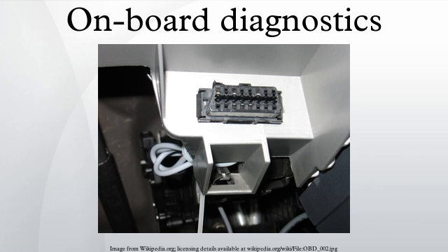OBDII diagnostic connector. The OBDII specification provides for a standardized hardware interface, the female 16-pin J1962 connector. Unlike the OBDI connector, which was sometimes found under the hood of the vehicle, the OBDII connector is required to be within 2 feet of the steering wheel. SAE J1962 defines the pinout of the connector;